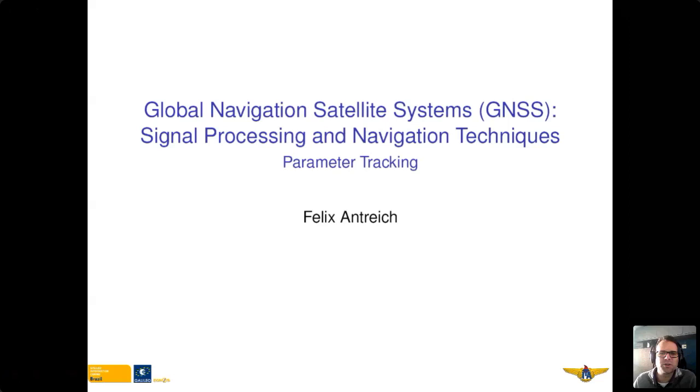But if you are interested, there's a lot of free software also available for signal acquisition and tracking. So it's easy to develop a small computer program, even working with real data, with this parallel time delay acquisition. And it is also quite fast, because you calculate all the time delays with one shot for each Doppler bin.